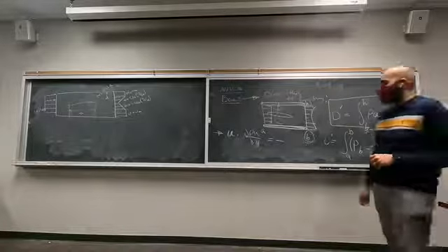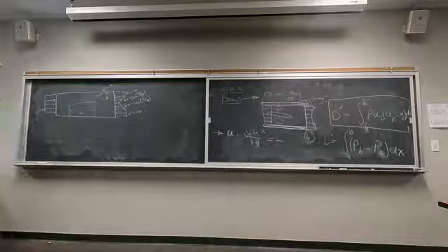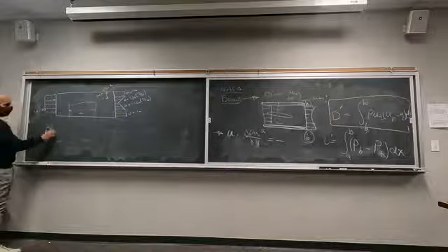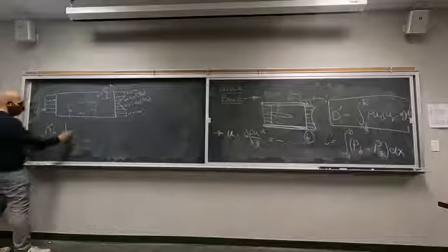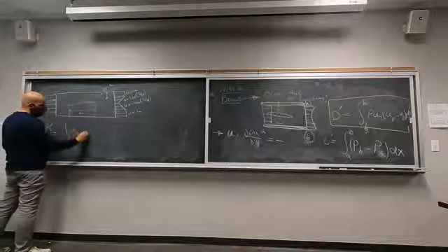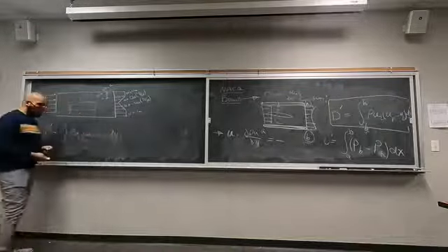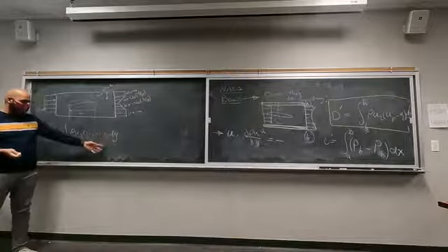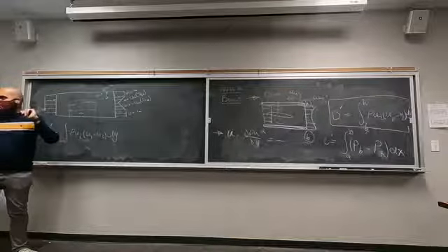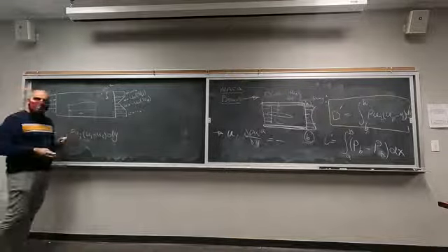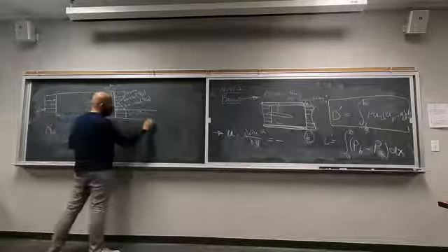Okay, think about it. This is the equation we want to solve. Your drag is going to be the integral of rho u2 multiplied by u1 minus u2 dy. So changes of velocity in the y direction is going to be important. We can actually divide this whole thing into 4 regions because we have 4 regions of change.